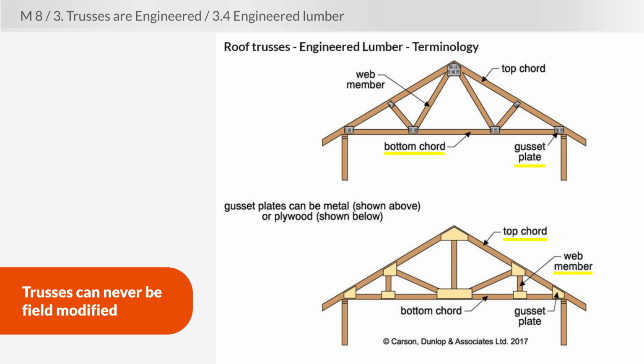Again, trusses can never be field modified. Now, when we say field modified, that means not changed simply by the decision of the carpenter or the homeowner. If trusses are going to be field modified, it can only be done under the direction of a licensed structural engineer.